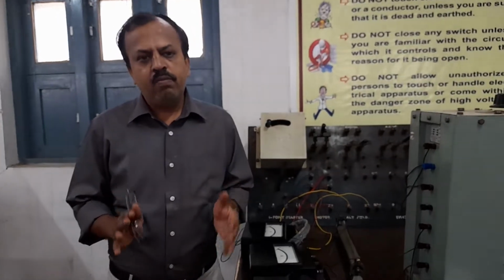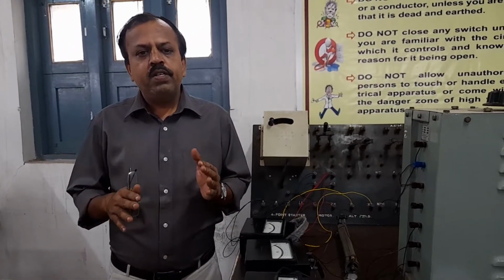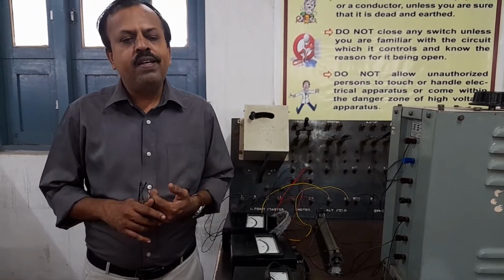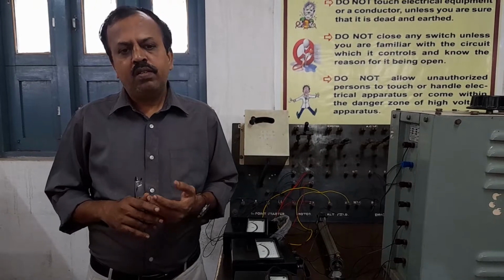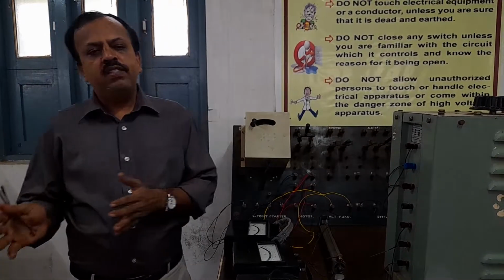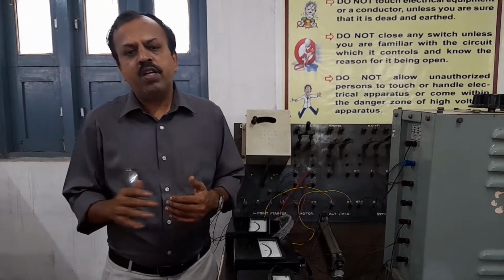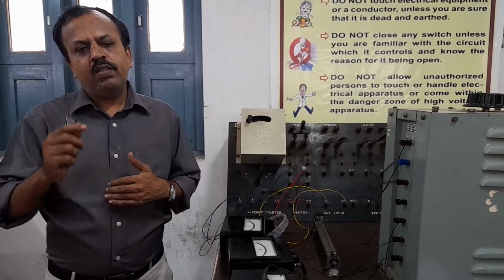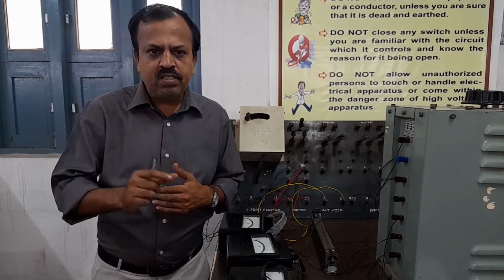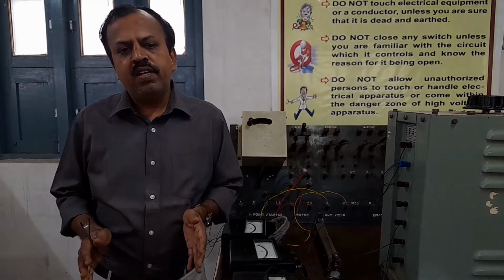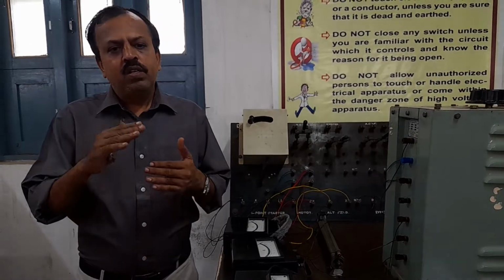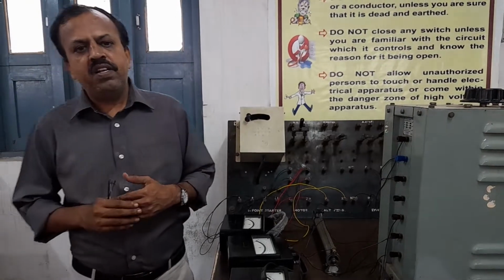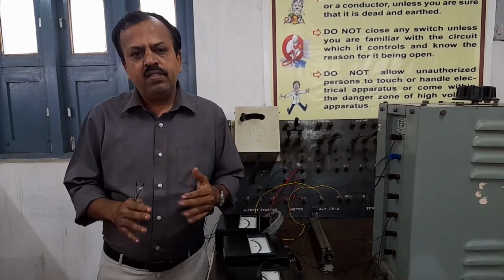In the case of cylindrical pole machine, air gap is uniform and hence the reactance offered by the armature winding is uniform throughout the air gap. Whereas in the case of salient pole synchronous machine, air gap is not uniform and therefore we observe very less air gap along the axis of the field poles and large air gap in between the field poles. So this will cause saliency in nature for the salient pole machine, and because of this saliency we will be getting the reactance non-uniform.